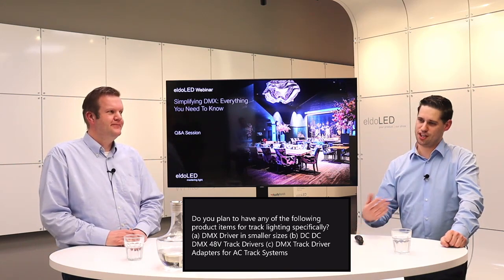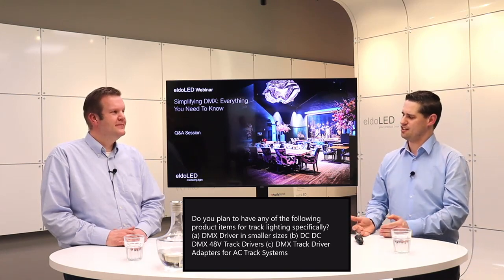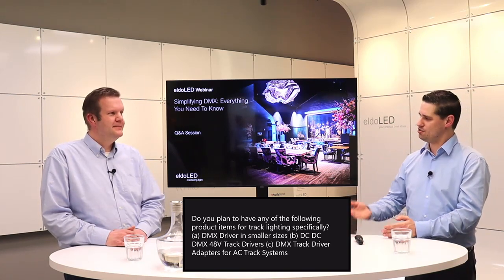No. And what I see, to be honest, from the industry is that the 48-volt track lighting is focusing on DALI. You need 3 conductors because you need the positive, the negative, and the shield. And no T-taps. And no T-taps, indeed. So track lighting is not the best way to do DMX on. You often see wireless DMX luminaires on those track heads. Possible.